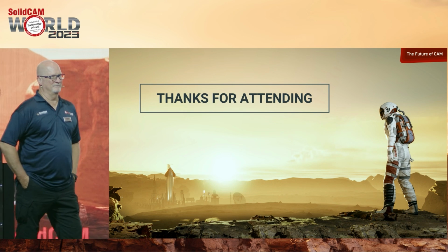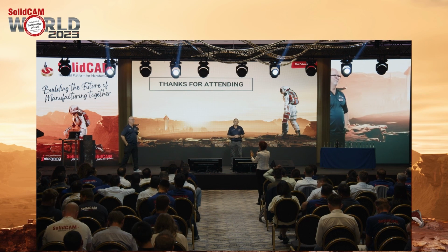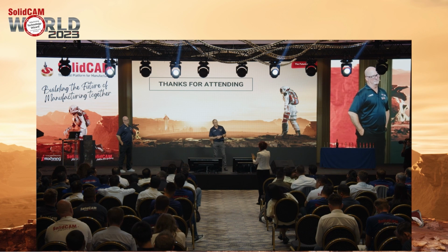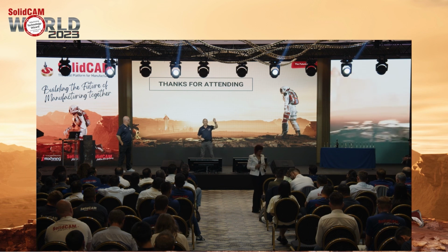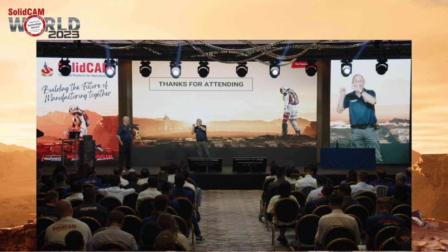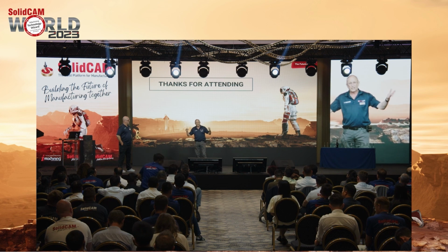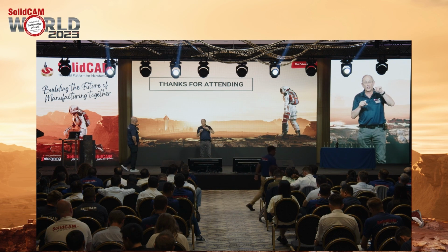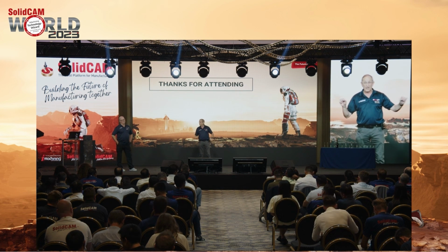Okay, so there's a question here for Sidney. Can the dynamic chamfer operation cut from larger diameter to smaller? At this moment, it starts from the small one to the larger, and then it goes back up. Maybe I didn't say this correctly, but it doesn't just go from the smaller to the larger. It goes from the smaller to the larger and then goes back down to the smaller.